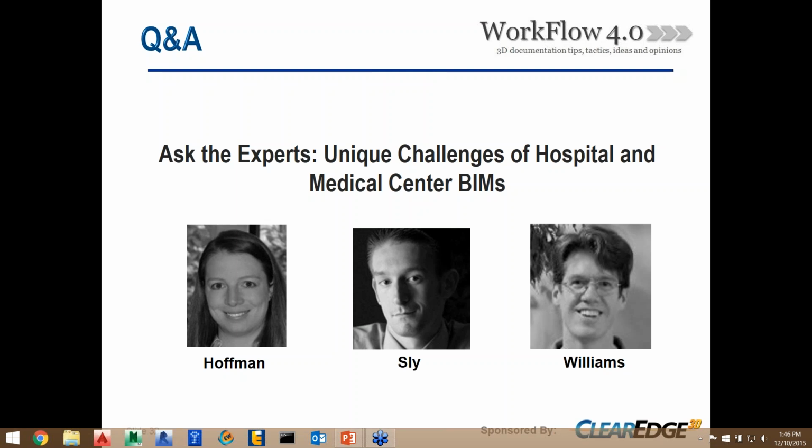because there are situations where targets are tough to use. I recently scanned something where there was not a single metal thing in there. So putting up spheres was pretty difficult, and trying to attach paper targets to a building that's 150 years old with dust all over it, they just kept falling down. So target lists would have been a great way to go had we felt comfortable enough to do it at the time. So it's something we'll be experimenting with in the future.